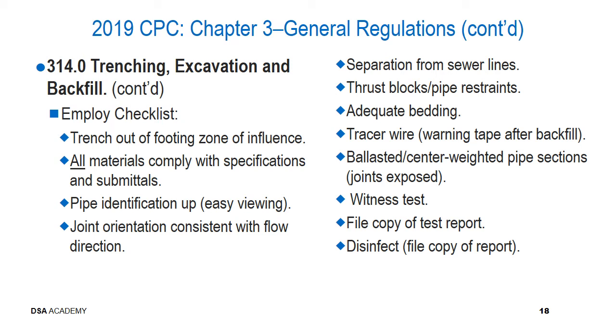Additionally, if it's potable water, this water is going to have to be disinfected. That generally occurs after pressure testing, after backfill, after all of this other construction process has been completed and approved. The other important thing to consider is to become aware of the disinfecting processes which are approved for the project.